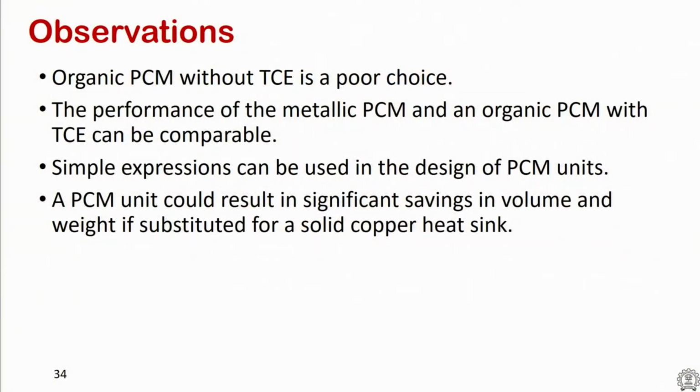The metallic alloy does bring you interesting benefits, but one has to understand its corrosion behavior and other related challenges, such as how reliable they are after n number of cycles and so on. Nevertheless, the organic phase change material with metallic foam may be a lightweight solution that is far better than metallic alloys. So, all these different options should be considered while designing these things.